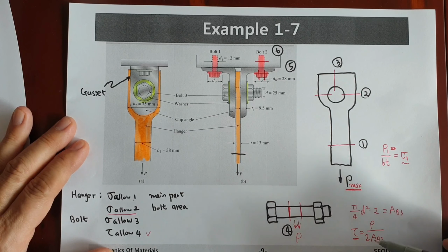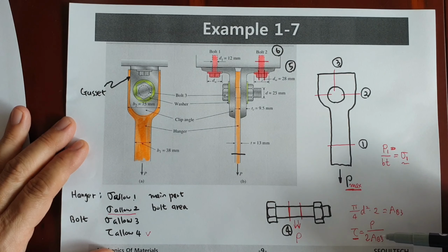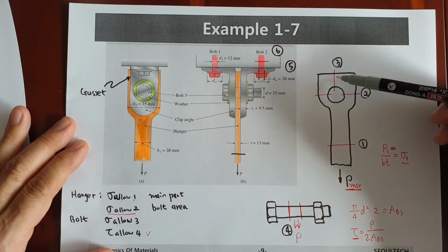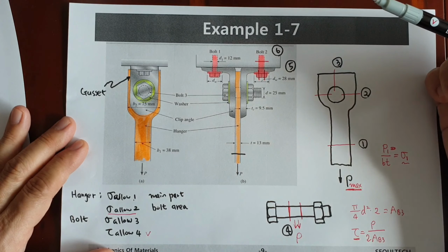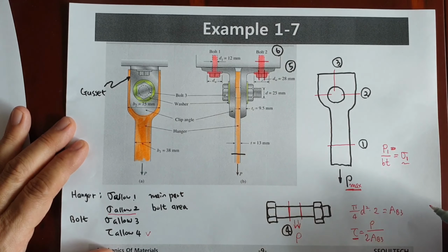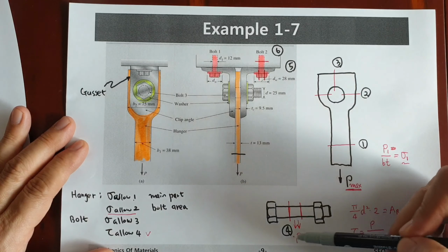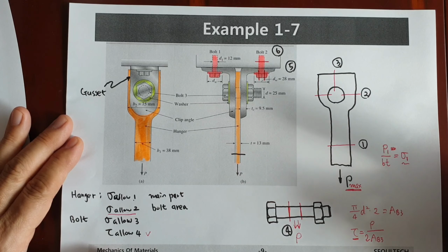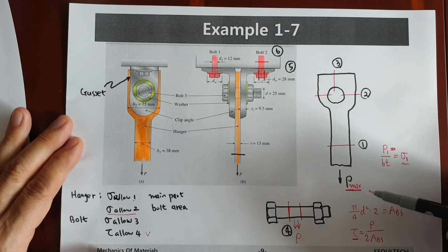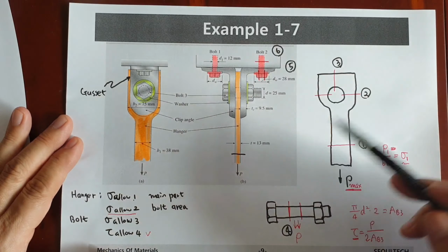Okay. In this case, we applied it to this bolt, but when we apply it to another side here as well, the toe of the gusset, and here the head of the bolt, we can apply it there. Then we can find the maximum P value, and we can compare P1, P2, P3, P4, P5, P6. Then finally, the worst case, we can select that value. That's the maximum allowable external force for this device.